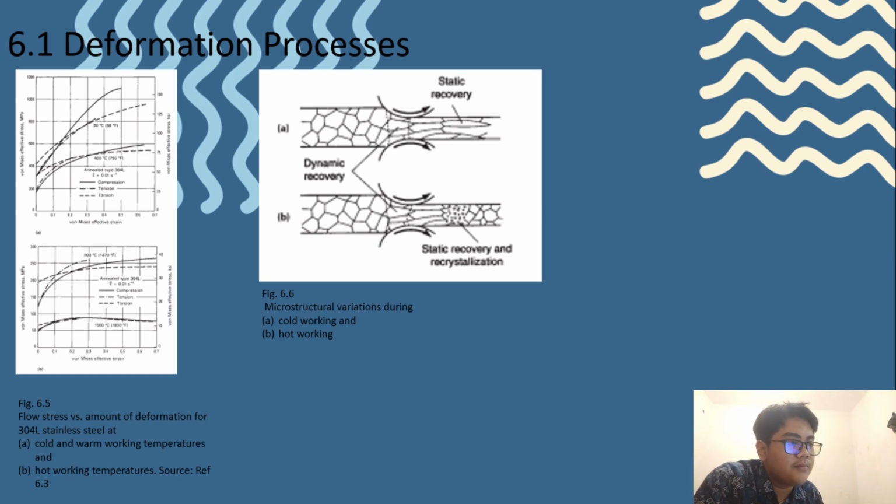Forming is performed through contact between the surface of the deforming metal and the tool. The nature of the material flow or plastic deformation primarily depends on the type of forming process that is used, the temperature, the applied loads, and the frictional stresses between the tool and the workpiece material.